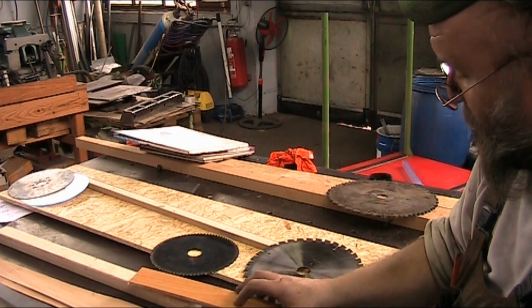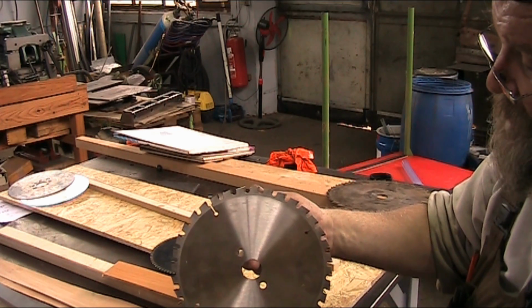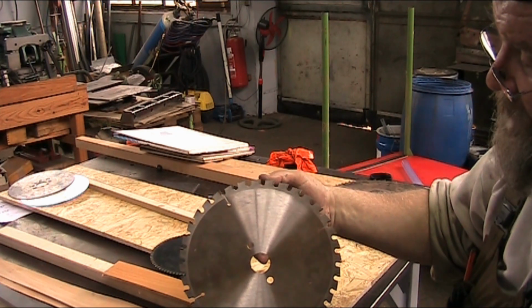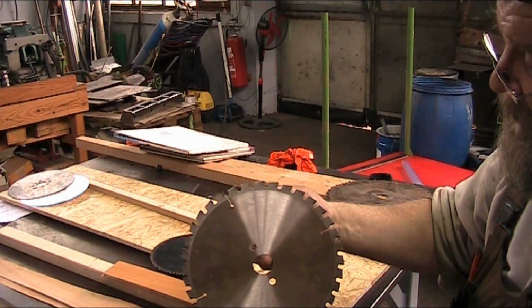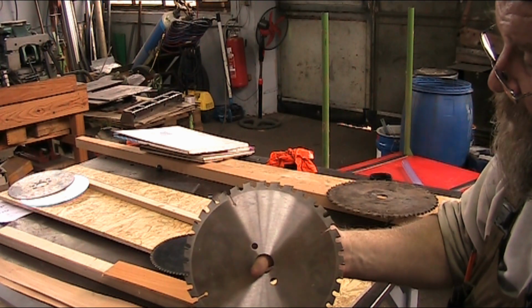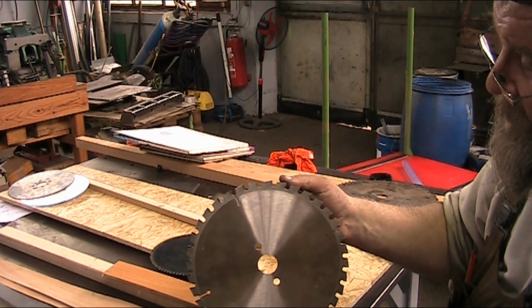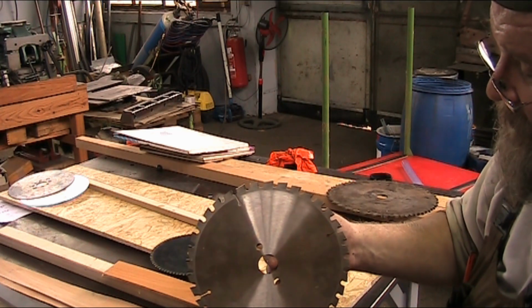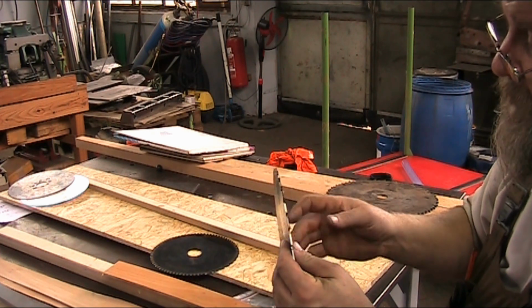Let's see here. Then we have this guy here. Like I said, this is one of those safety saw blades, and as you can see, the ridge of the tooth doesn't slope off very well. So this means this is one of those quote-unquote anti-kickback saws, and you can't really feed this guy too terribly fast without running into problems. Now this has an alternating grind, and a picture is still right here.